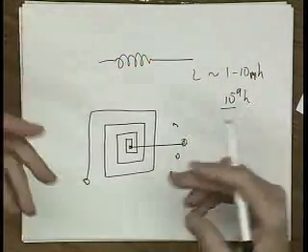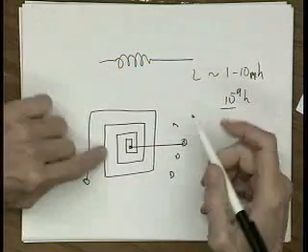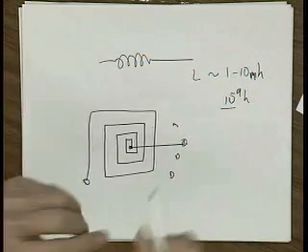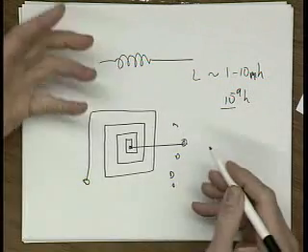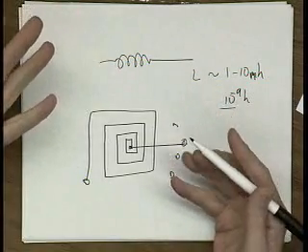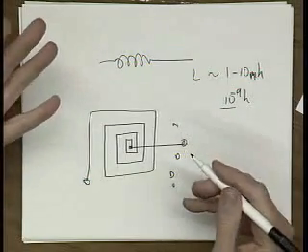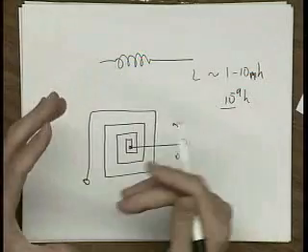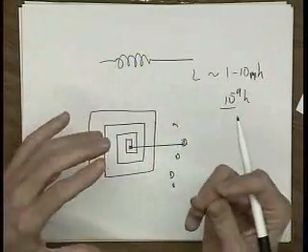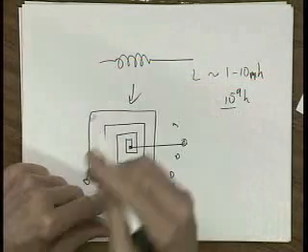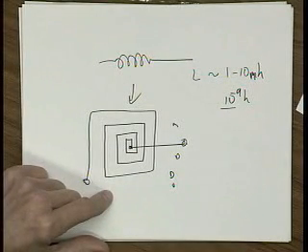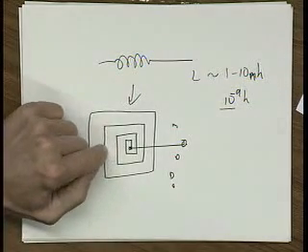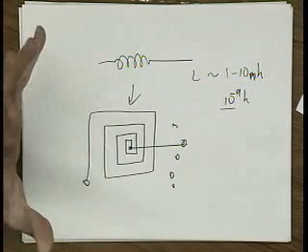As we go to more fancy technology, the inductor stays the same size. We shrink our transistors down. They get smaller and smaller, but the inductor just sits there big and happy, costing more and more, effectively, because it's a per unit area cost. So it's getting to be a challenge of how to design radios where you don't use inductors, just like you didn't want to use resistors because they were expensive. If you could try not to use inductors, it's really a good thing to do.